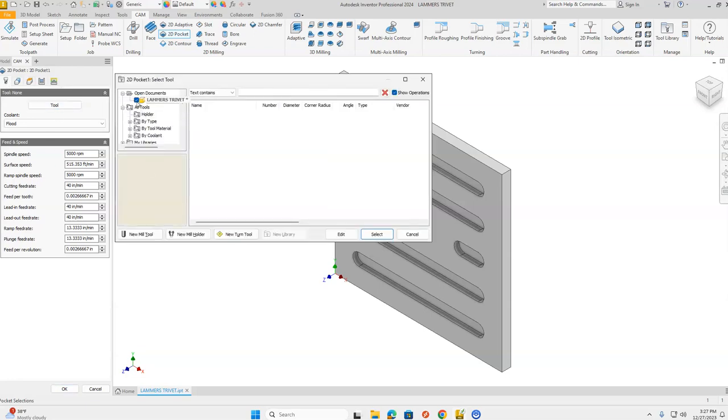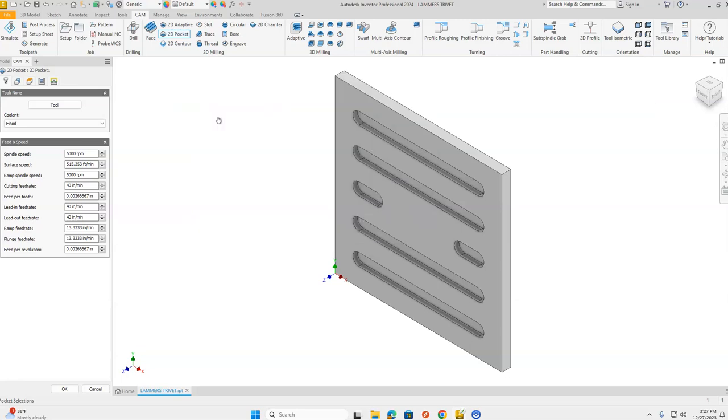We're going to go on the menu in the left hand side, and we're going to scroll down just a little bit, and we want to find underneath Sample Libraries, End Mills. Select End Mills, and we want to choose tool number 2, 1/4 inch flat end mill. You're going to see an icon of what it looks like right here. Yours should pretty close to match that. Then we're going to go to our next tab.